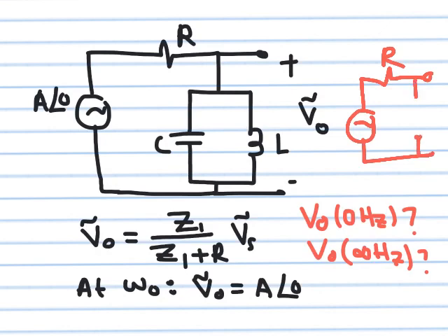So this means the output which I measure here will follow the source, because this branch is open circuit. At resonance, in this case, you get maximum transmission. Remember, this circuit is different from the one we had earlier. Before, the L and C were in this branch and the R was here. When we switch the order, we convert the circuit from a notch filter, or band stop filter, to a band pass filter. So at that specific frequency, V output will be equal to V source.